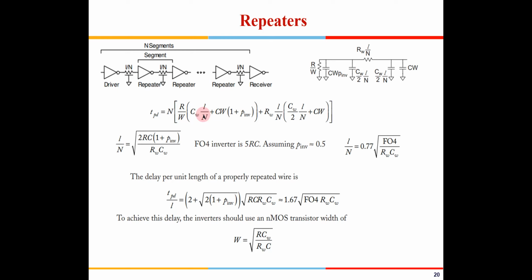But by adding inverters, shouldn't the delay increase? No. What happens is, these inverters have a threshold. The moment this input reaches close to half, this will trigger these inverters. That is why it reduces the delay. Is it okay, Indranil?